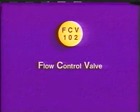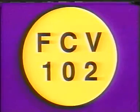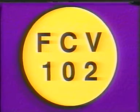Valves that are part of an automatic control loop are called control valves, and the letter C is always the middle letter in the valve symbol. Let's review the location of indicating letters. The letter for the process variable is always first.